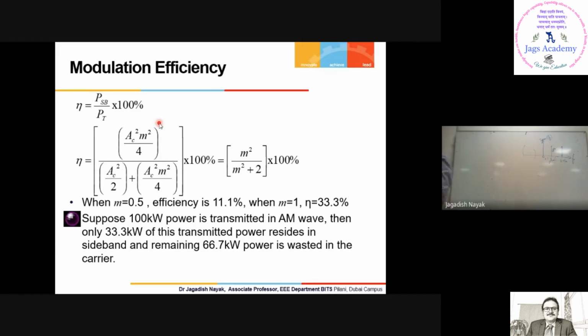Okay, now what is this? This is spectrum of DSB-SC wave. Yes or no? Spectrum of DSB-SC wave. See, this is minus fc. Now, how do you remove one of the frequency component in this? Use filters, right? You use filter. So how do you filter this? Multiply with the transfer function, okay, with a band pass filter.